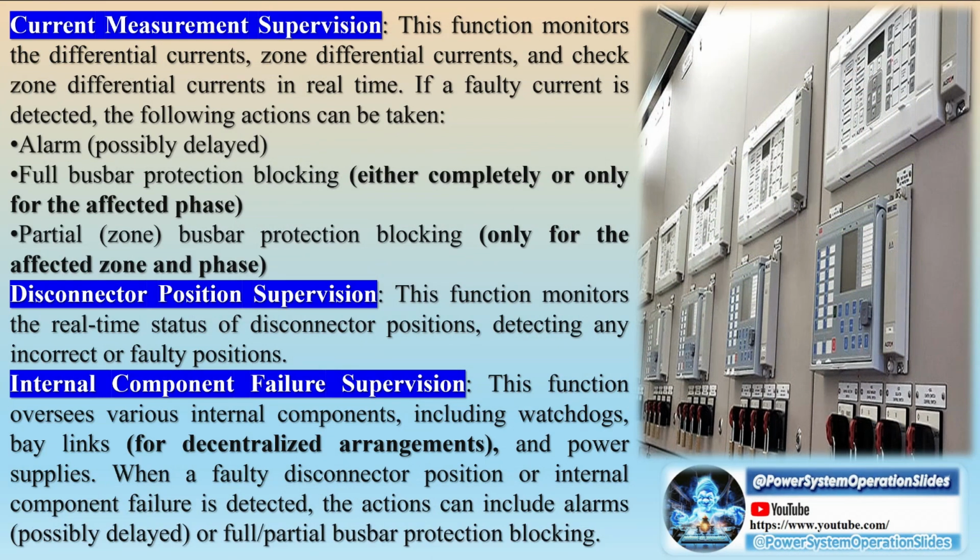Modern technology allows for the protection of complex substations and ensures continuous protection even during reconstruction phases, which often require temporary operations. A key feature of numerical relays is their built-in monitoring system, which detects and alarms faults within the equipment. Main types of differential current protection relays: low-impedance differential protection and high-impedance differential protection.